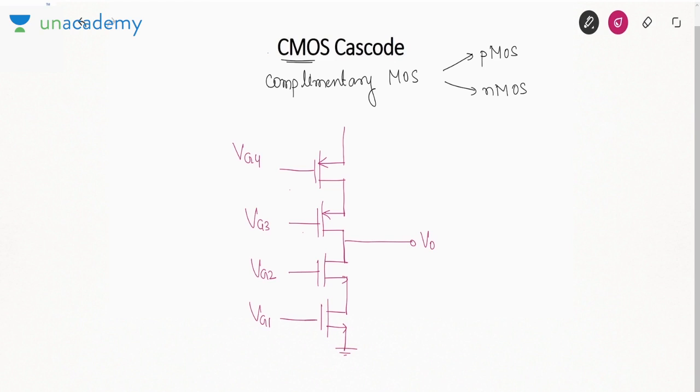Okay, this is Q1, Q2, Q3, Q4. So I told you, when you want to find the output resistance of, suppose, NMOS transistors, which transconductance will you use? The transconductance of the transistor near to the output, which is near Q2: gm2 into r01, r02.